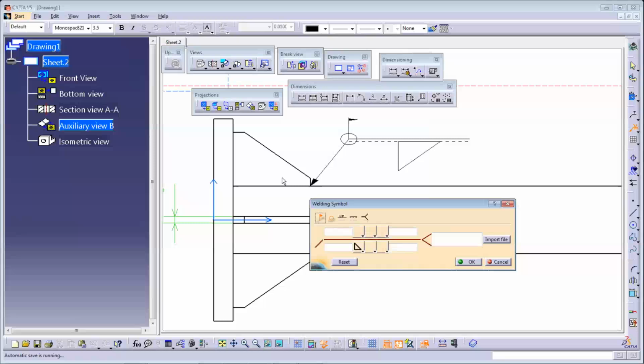Okay, in that situation we have to weld it in the field only. You cannot weld it in the workshop and then install it in the actual location. In that situation, the field symbol needs to be on. This is the design information on whether to weld this part in the field or in the workshop. If you turn this option off, you can weld these two parts in the workshop. So this is important.